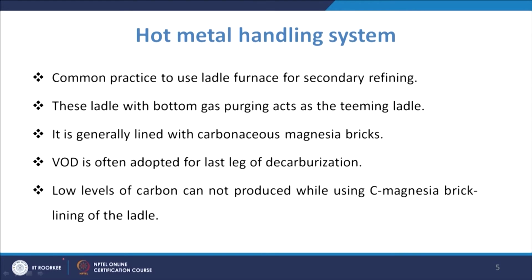When we want an even smaller amount of carbon, for the decarbonization, many a times we use the VOD process also. And while using the magnesia brick lining of the ladle, we can also ensure a low level of carbon.